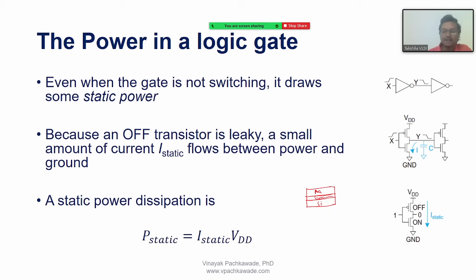So this is your MOS capacitor, and what we see here is that you have this gate terminal. There is some leakage through the dielectric, so the current can still flow. It's also called the tunneling effect, where when you deposit charges on top of the gate, charge carriers can penetrate through the insulator and go inside the silicon. That is an adverse effect, and it is more and more pronounced because of the scaling effect. In modern transistors, this effect is challenging to address, but we are still managing with material science to get rid of it.